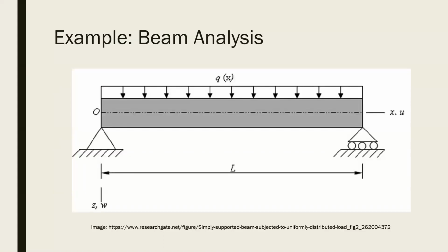Okay, so let's do some examples comparing what you would do in a previous class versus what you can do with finite elements. In a previous class, you've probably had a problem like this where you were asked to solve for the deflection in this beam, right? So you have a beam, you have a pin support on the left, you have a roller support on the right, you have some distributed loading, and you were asked to solve for the deflection, okay? And that's great. We have equations for this. We have the Euler-Bernoulli beam equations, and we can solve for it, right?